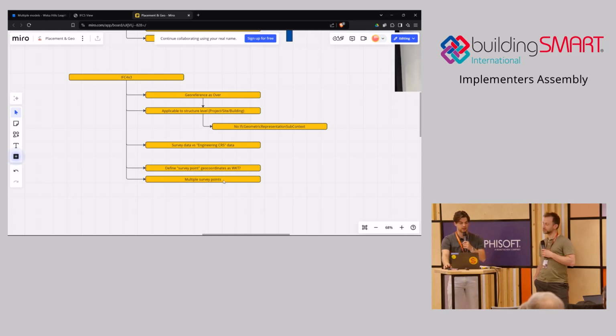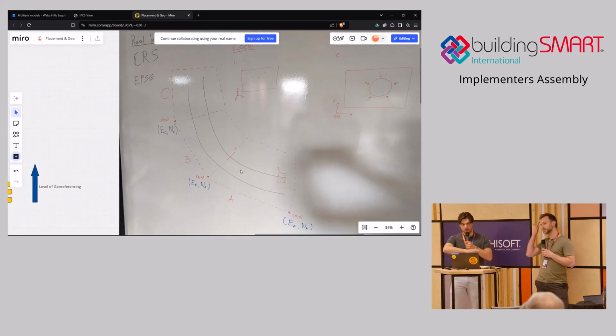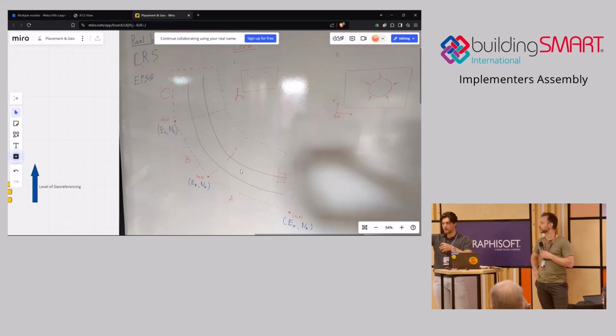If, as I understood, you have a very long project, then the alignment is going to be in some EPSG registered CRS, and then models along this alignment are going to be modeled in Revit or whatever, and then those sections like the tunnel entrance, tunnel linings, then maybe some bridge even further, they are going to have different coordinate reference systems, each of them. And then you can calculate the transformation because you're using these WKT strings and there's software that can calculate it, but the question is always from what to what.